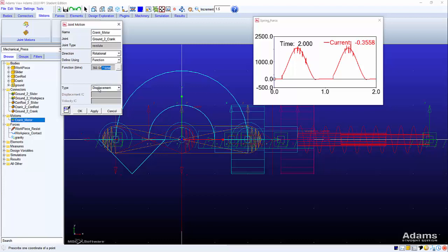If you specify the velocity, then you need to specify the initial value for the displacement, because this is kind of a differential equation. If you specify the acceleration, then you need the initial displacement and the initial velocity. So now let's assume we control the constant velocity with initial displacement 0, like this. What will happen to this equation? This equation should be changed now, because this will not make constant velocity. This is going to make the velocity change with time.